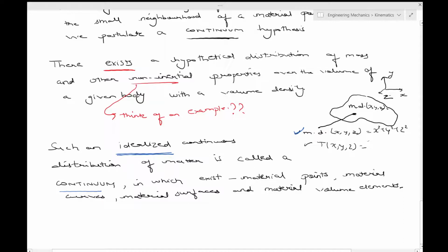There are a few exceptional engineering situations where such a continuum hypothesis may not work, but for most cases it works, and that will be the part of study of at least our course. Perhaps later on, if you take up a course in molecular dynamics or quantum mechanics, you would see those special cases where the continuum hypothesis breaks down and is no longer valid. But for most of the engineering applications around you, I can assure you that this idealization of a continuum works reasonably well.